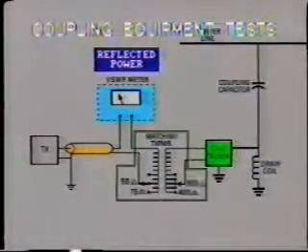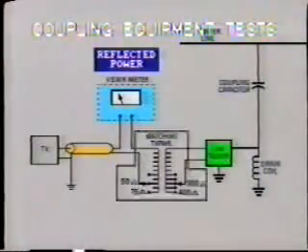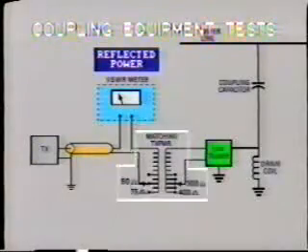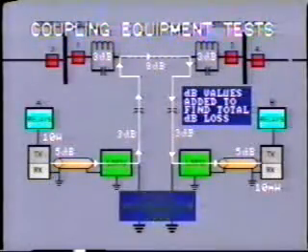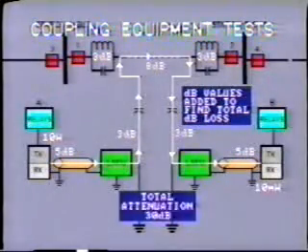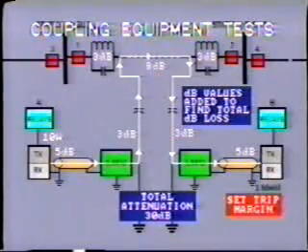At this time, the final adjustment of the impedance matching transformer taps can be made. Measurement of signal loss end to end with the carrier in service and at different frequencies. Adjustment of trip margin at the receiver.